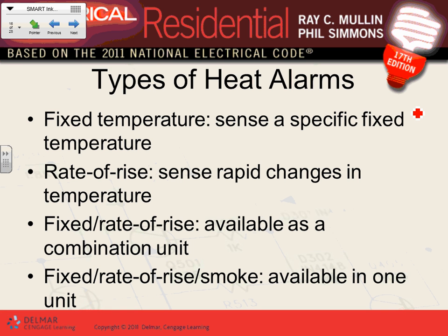Then for heat alarms, they have multiple technologies that they use. We need smoke sense for smoke. What do you think heat sense? Heat. Okay, I'm not asking you for heat detectors in our project. If you want to put a heat detector in a building, a commercial building, in a house, where would you put a heat detector? Anybody can guess? No, where in the house? Like in the kitchen, living room, bathroom? Kitchen. Kitchen would be a good application for a heat detector.